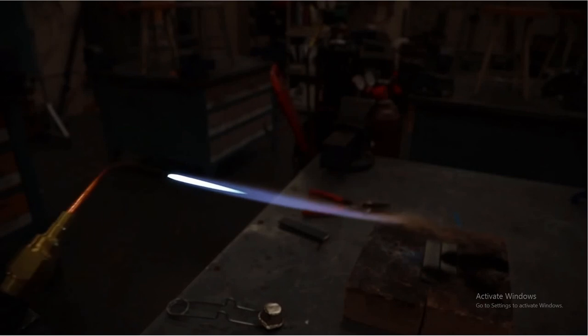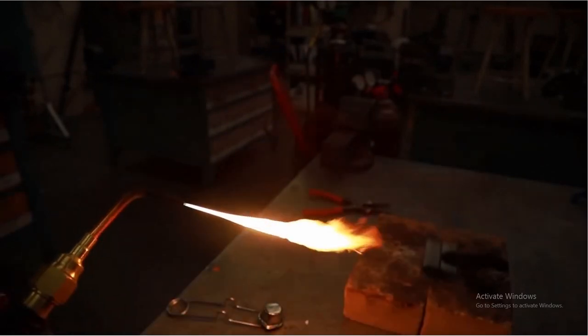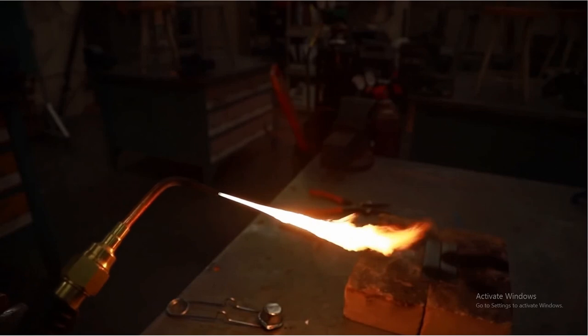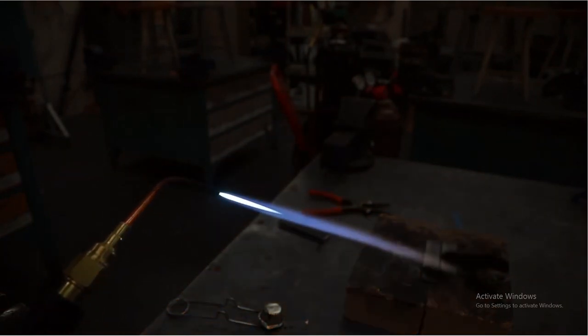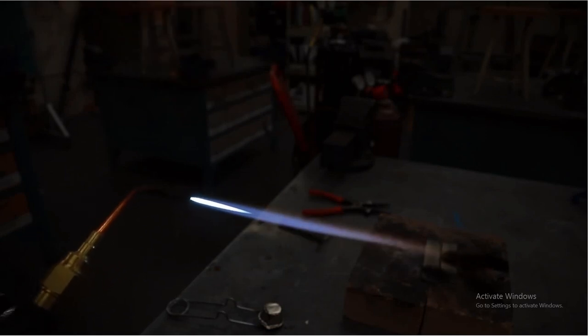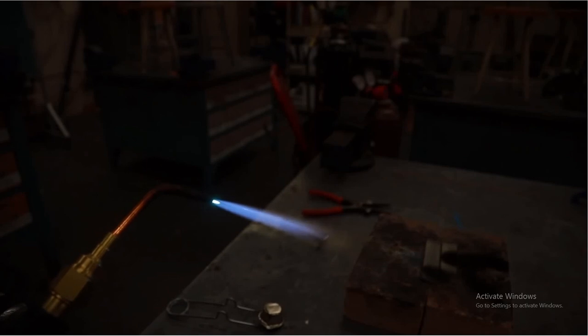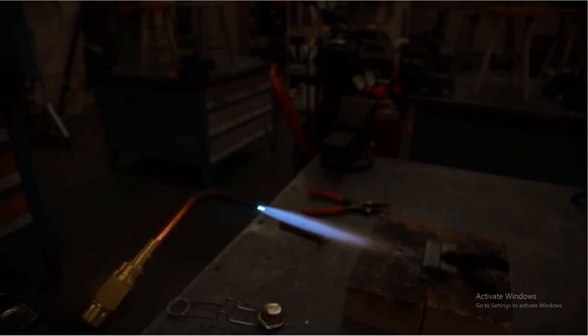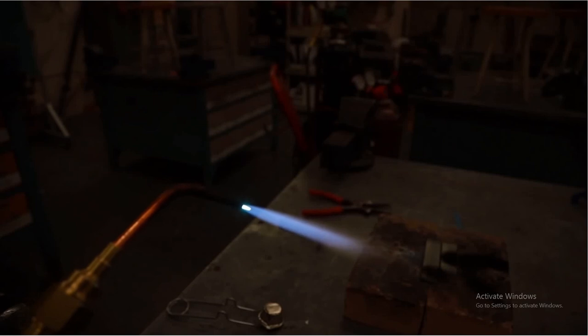So I set the exposure on the camera down a little bit so you can see the 2 different cones. When you first have just acetylene, you've got that, add your oxygen, and you're going to see 2 different color flames essentially coming out. We've got a short bright one and a long one there. I'm going to add more oxygen until I have a very nice little cone that's maybe less than 1 centimeter long. All right, let's do some welding.